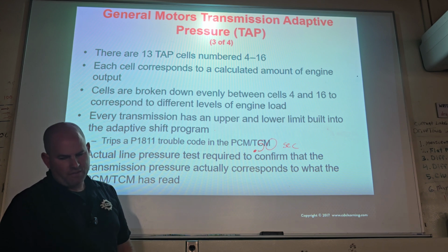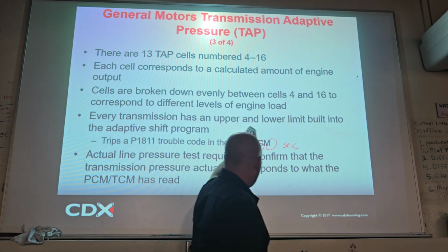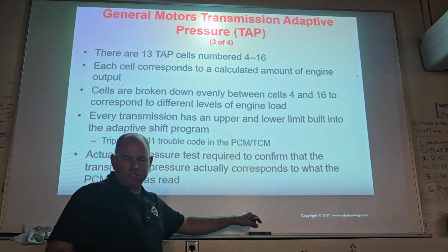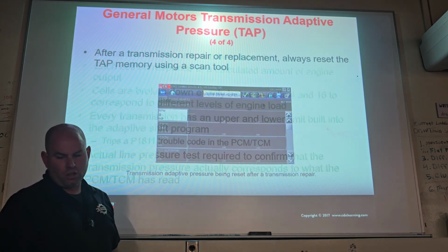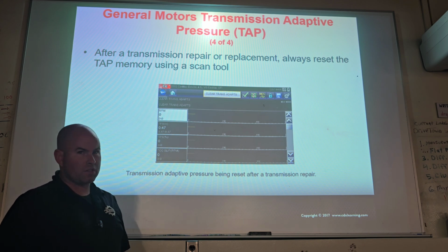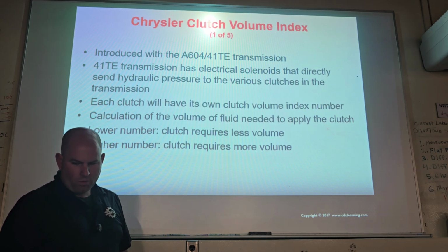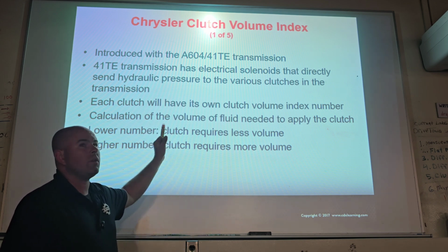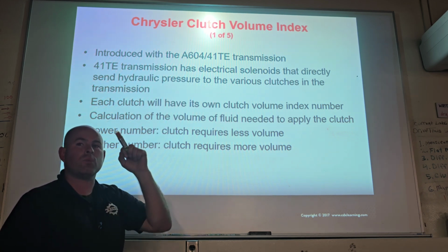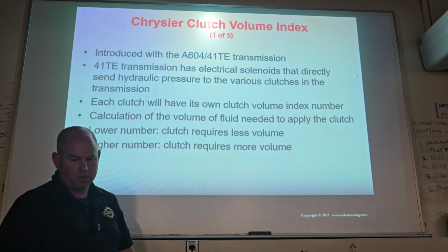So this one even would break down into different cells. It'll actually show you where it's at in the adaptation process. You can even tell if it's getting close to max. If you really wanted to know, you could tell if this transmission's almost worn out. Cool. And then remember, when we do the replacement, you have to reset that for it to really function. So that's a mandatory step. You got to remember to do that.